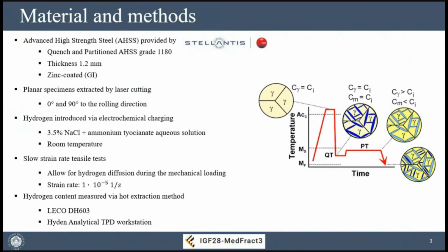It's a very interesting material because it has very nice stamping properties, so formability properties, but due to this retained austenite content, it can present a risk of TRIP effects, so transformation of austenite into martensite due to the application of strain, which can be the strain applied during forming, or the strain applied on our car body due to an accident or some unforeseen event, that can change the microstructure of our material and produce fresh martensite.